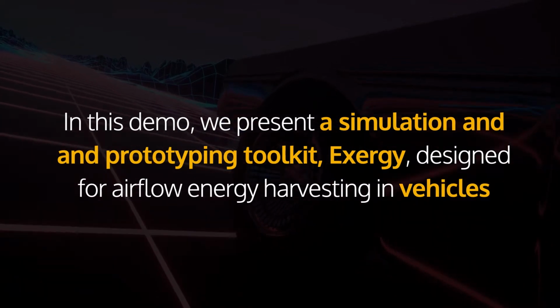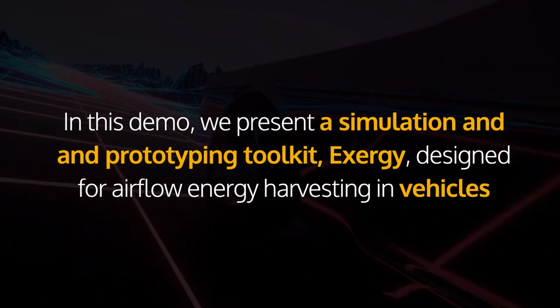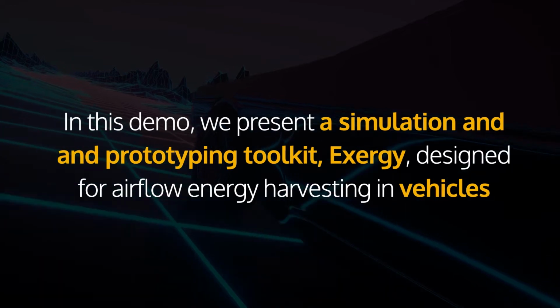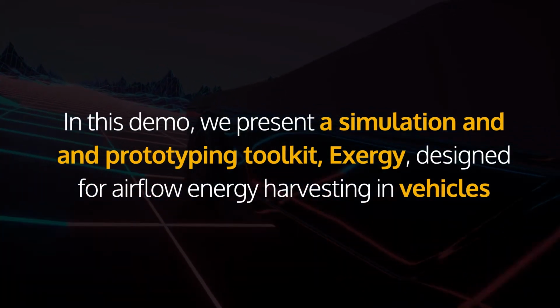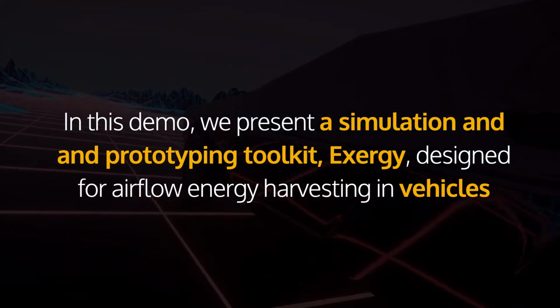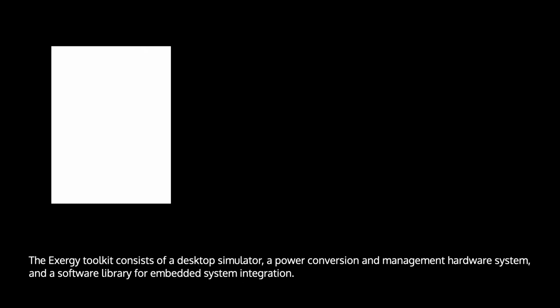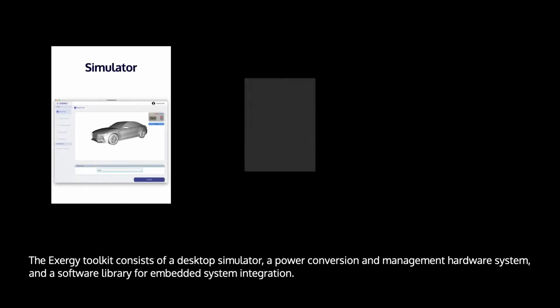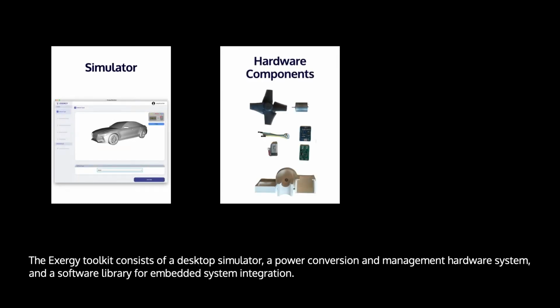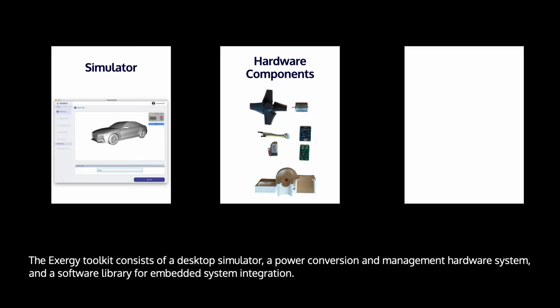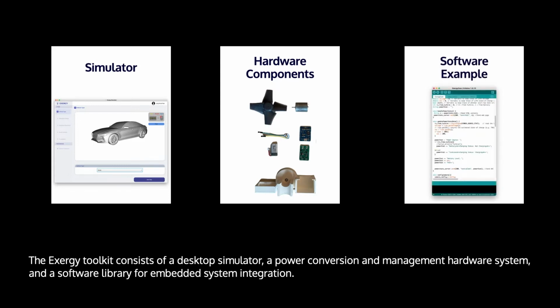In this demo, we present a simulation and prototyping toolkit called Exergy, which is designed for airflow energy harvesting in vehicles. The Exergy toolkit consists of a desktop simulator, a power conversion and management hardware system, and a software library for embedded system integration.